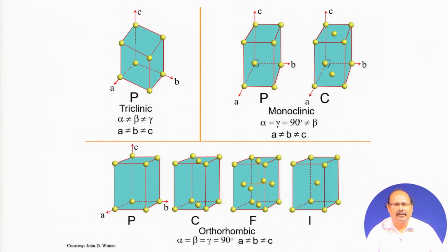All the angles between the axes are orthogonal, 90 degrees. So, this is the primitive lattice here, and this is the C face centered lattice under the orthorhombic crystal system, and I define why this is C face centered. Apart from the lattice nodes at the 8 corners, it also lies at the center of the 2 C faces, one above and the other below.